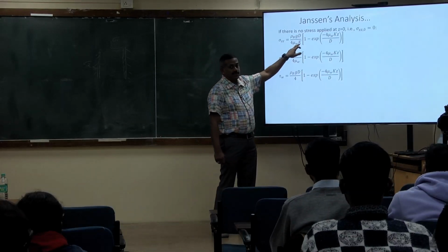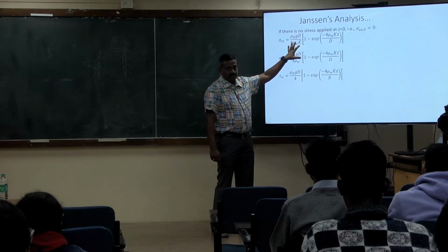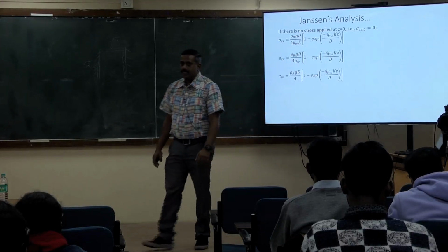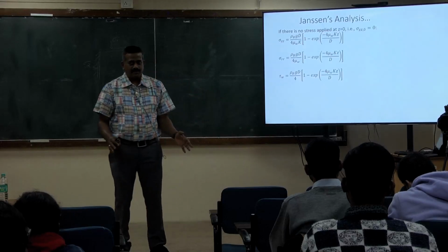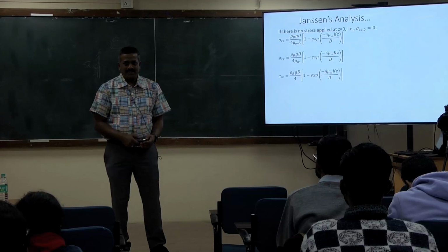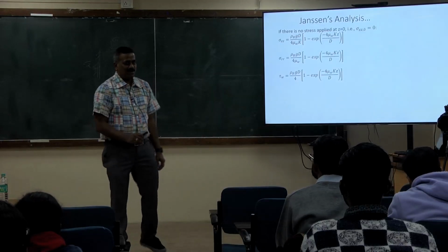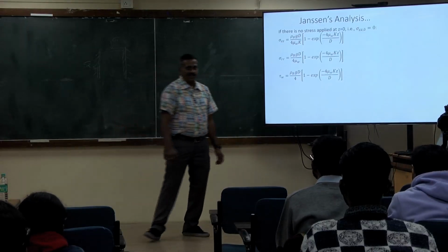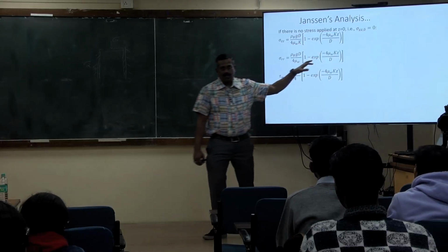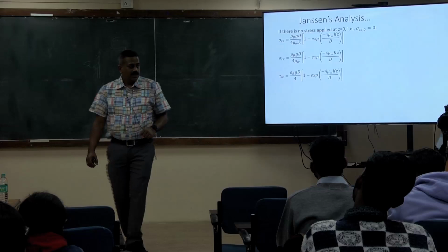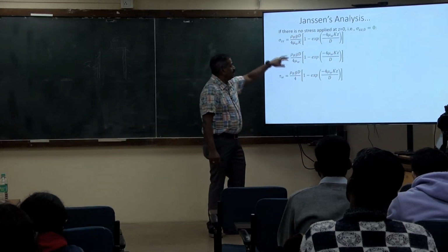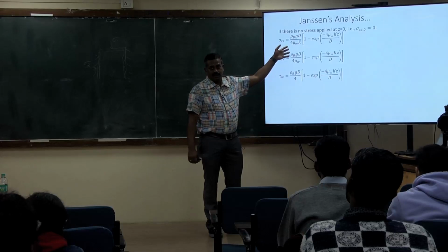the only difference here is K, the pressure ratio. It's calculated from the angle of internal friction, right? Anyone remember the formula? Okay, sine phi, it's not sine theta, just a small correction. That's 1 minus sine of the angle of internal friction, over, well, that's where we use the angle of internal friction to calculate the pressure ratio. You calculate either one of them, and then using the pressure ratio K, you calculate the other stress, either vertical or radial.